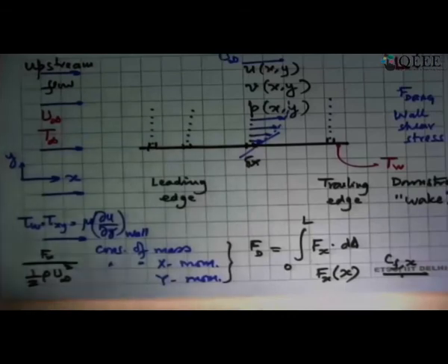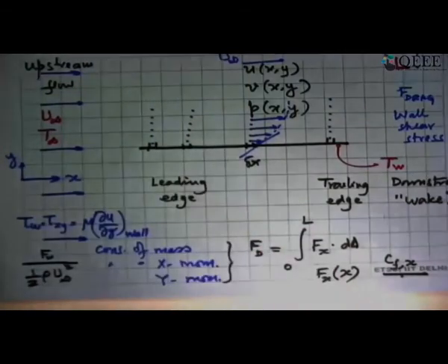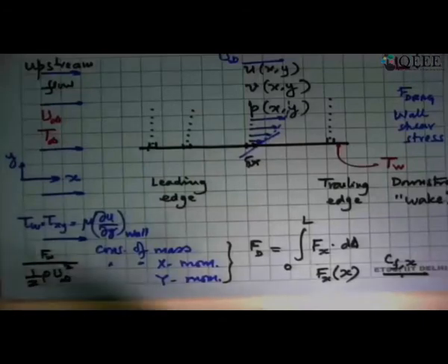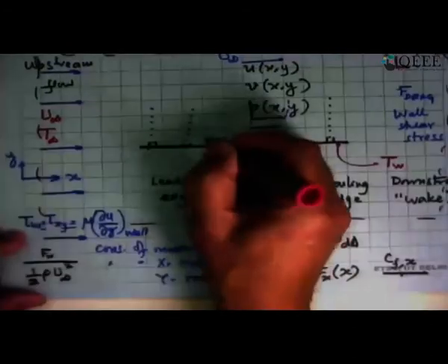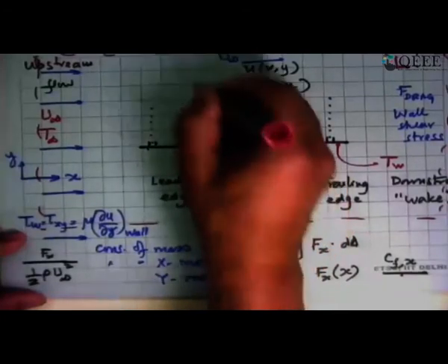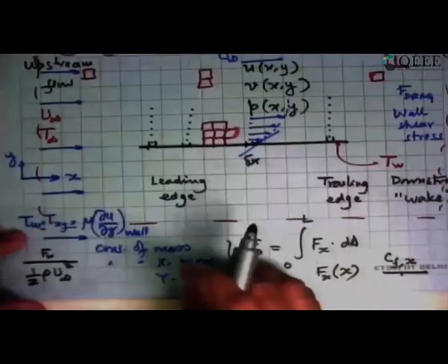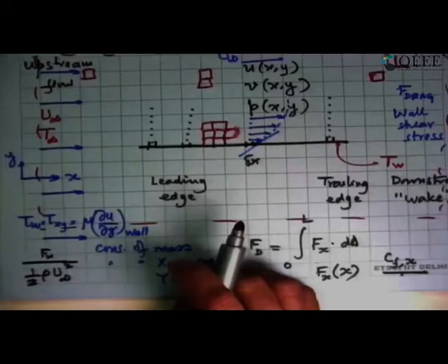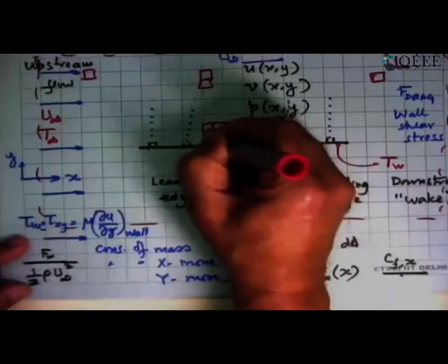What one does these days is say, yes, I will solve this equation. For a laminar boundary layer, for some simple cases, there is an explicit solution. The exact solution is there. In the practical world, what we do these days is to say that, look, I will solve this equation numerically, which means that I will define my domain, which is a big thing like this. I will just make small elements all over the place, everywhere, including here, including there, and get millions of these elements. I can change the shape and size and location depending on various considerations, and then we will write the equation at each one of these and solve them.